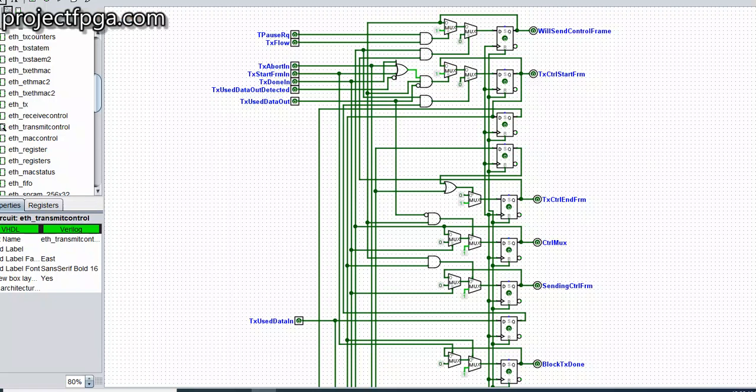We use flow control. Let's take an instance where the receiver is busy and the transmitter keeps sending more and more data. So the receiver can equally send a signal to the transmitter telling it, hey, hold on, I'm very busy. But in half duplex mode, the receiver keeps receiving, so it cannot send feedback to the transmitter. So that's why this module works only in full duplex mode. Therefore, this is the mode we will be using.